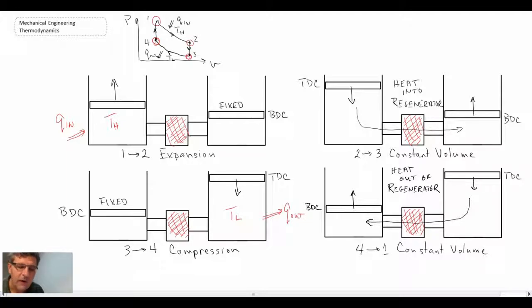So those are the 4 steps for the Stirling engine cycle. And so you can see that in order to implement this with a mechanical system, that is the Stirling engine, the crankshaft, and the connecting rods, it's a rather complex process because sometimes the pistons are moving and at other times they're not moving. And that's one of the tricks of the Stirling engine, is to make one that is balanced, has very low friction.